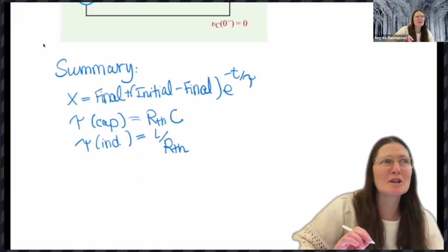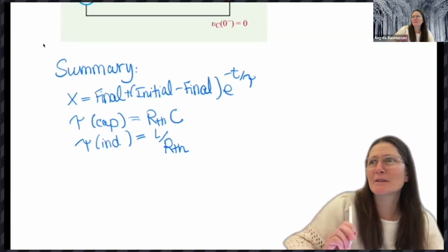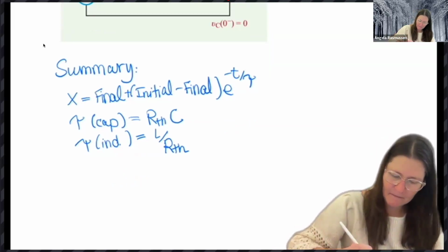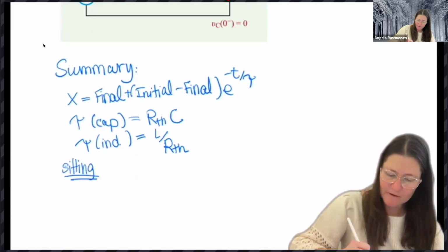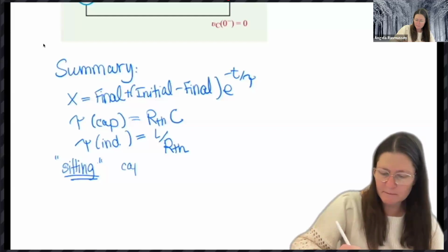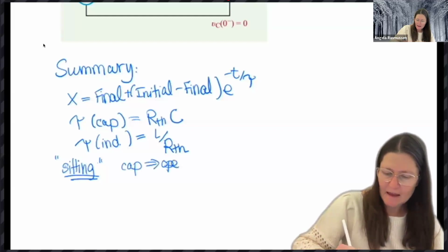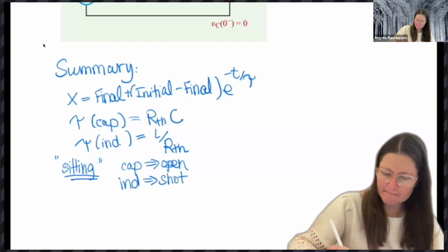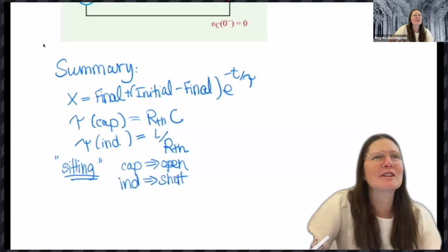What other things do you remember? When the capacitor has been sitting and charging, it will be open circuit, and the inductor will be short, correct.